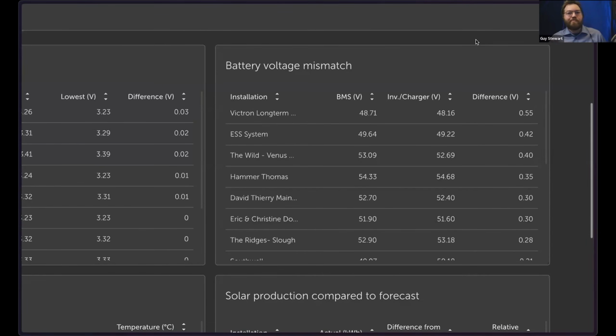All that's normal. What's not normal is sometimes you'll have a fuse blow inside that system along that DC bus, and you'll have a divergence in the voltages. It can be very confusing why that happens. You might get ripple alarms from an inverter charger, and you think, oh, there's a problem with my inverter charger, it's broken. No, it's not. It's just a fuse is blown inside it.